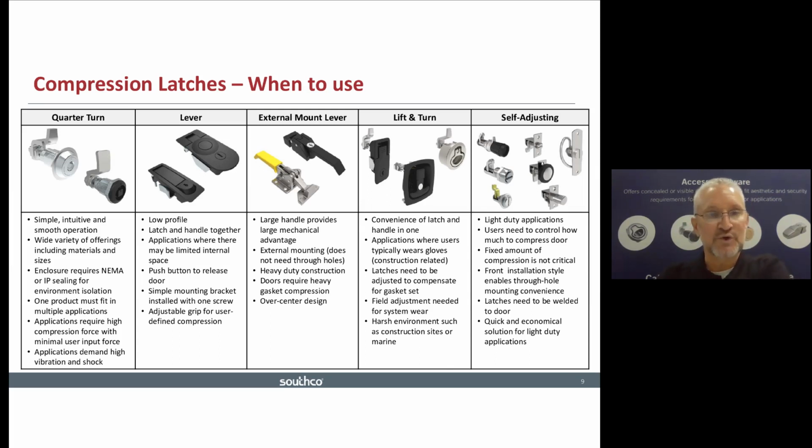So first, the quarter turn family. As the name implies, these latches operate by using a simple rotation motion on the head, which provides 2 interesting functions of the latch itself. As you rotate the head or driver of the latch, the cam underneath the keeper of the fixed panel rotates a quarter turn, and then you get a second function pulling that cam forward to provide compression.